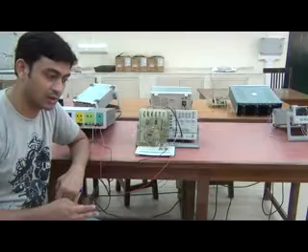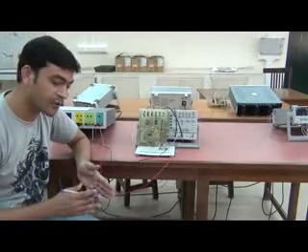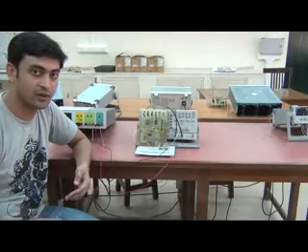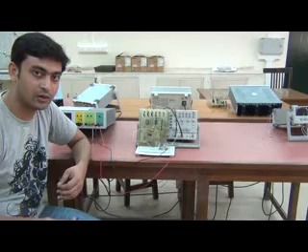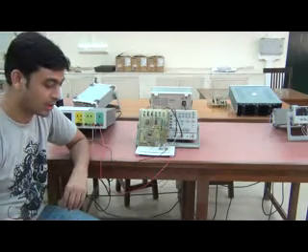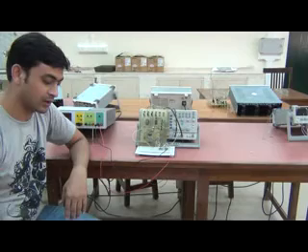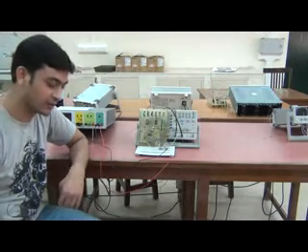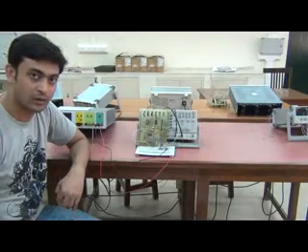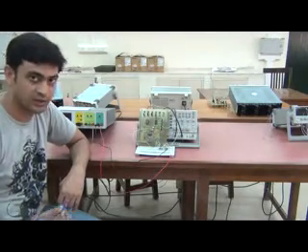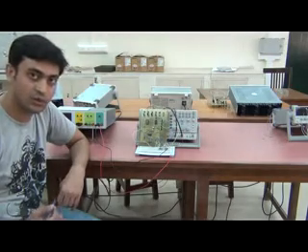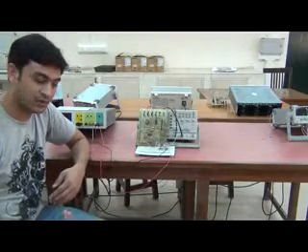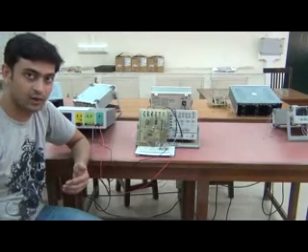Either the normal output can be used as a clock, or the inverted output can be used as a clock. That is either Qn or Q bar. Now, a divide by 8 ripple down counter will have a sequence from 111 to 000 state, that is from 7 to 0 in decimal form. The number of bits required for this sequence is 3.